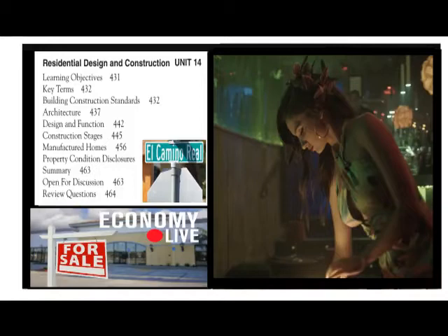have to comply with all local, national, and federal requirements regarding site utilization. A soil engineer's report, a test of the ability of water to drain, percolate, through the soil, seismic analysis, environmental impact report, and other studies may be necessary. The previous use of the site might dictate removal and replacement of soil if hazardous materials were stored or present on the property in the past. Sites identified as brownfields by the Environmental Protection Agency require extensive remediation.